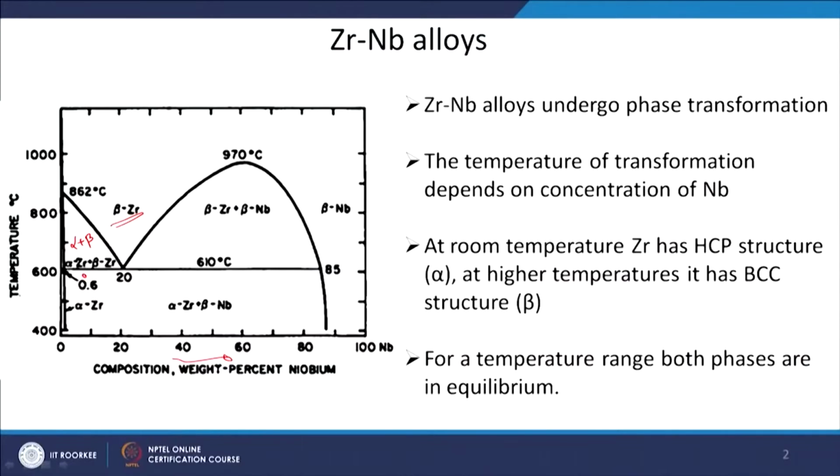For example, I can do deformation at different temperatures here, all these points I am pointing at, and the constitutive equation will be developed for all the temperatures together, without taking into account the different crystal structures present at different temperatures. We feel that is going to put a lot of error in the calculation, because different phases behave in a different fashion.